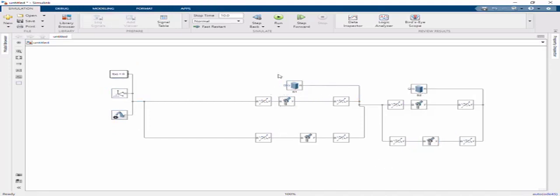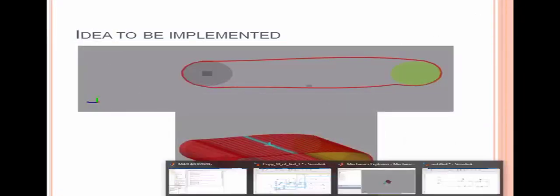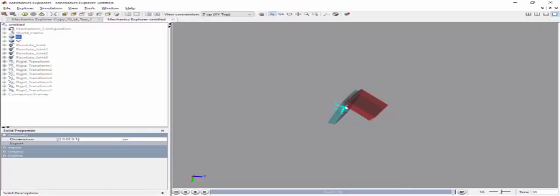So these revolute joints are just giving us some very limited degree of freedom, which is the rotating freedom for these two parts, as you just saw. The force which causes this rotation is the gravitational force that I created in my mechanism configuration.